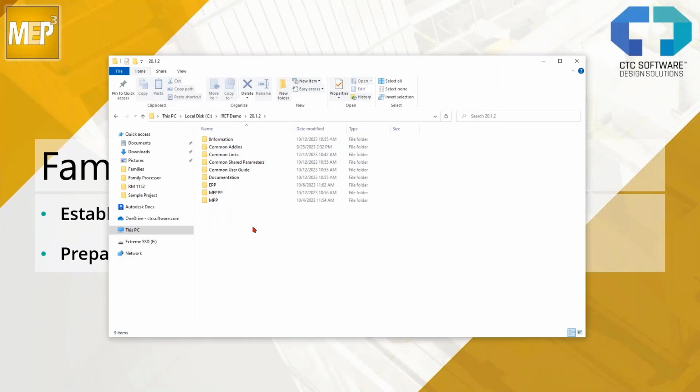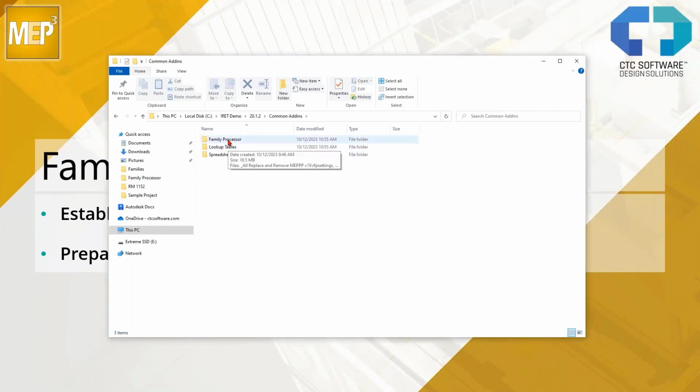So when you download the MEP Productivity Pack, you're going to get all of these different folders. You get some basic information, an add-ins folder, your linked models, your parameters file, the user guide, additional documentation, which helps for starter project setup and things like that, and then all your content. We're going to focus on the common add-ins folder for today, specifically the family processor folder.